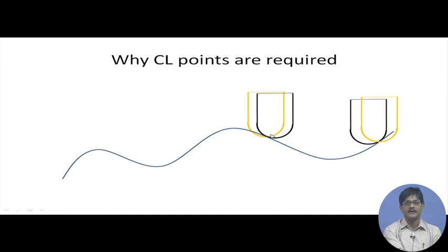Having accepted that, we can uniquely place it. In what way? We will draw the normal emanating out of the surface at this point, and a radius away from the surface, we will select the center of the cutter spherical end.